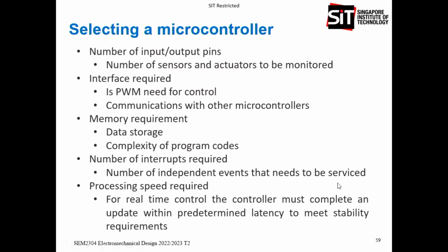Okay, how do we select the microcontroller? Well, you'll find that for all microcontrollers, the number of pins that you can use for your application is limited. So there will be a finite number of digital pins and a finite number of analog pins. So you must make sure that the number of I/O pins your application requires can be provided by that microcontroller.